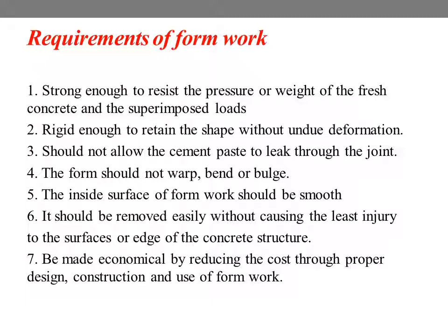Formwork should be made in such a way that it can be removed easily without causing the least injury to the surface or edges of the concrete structure. As formwork does not contribute anything to the stability of the finished structure, it should be made economical by reducing the cost through proper design, construction and use of formwork.